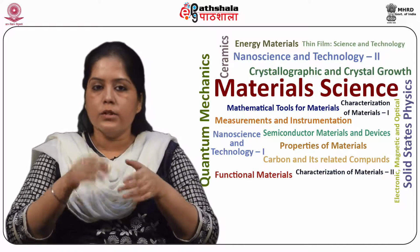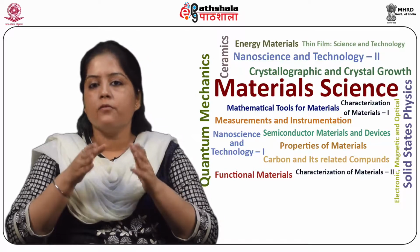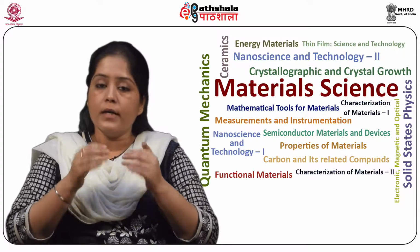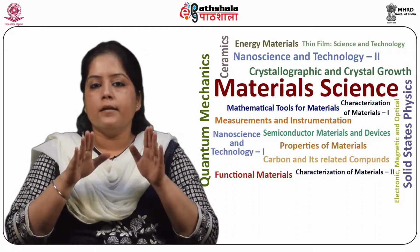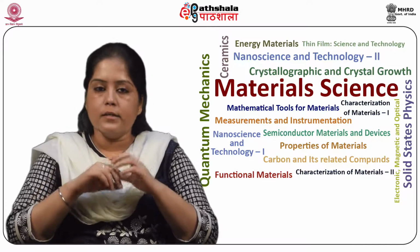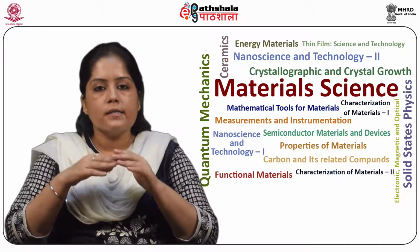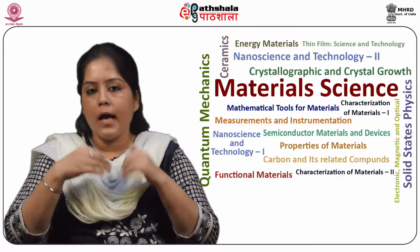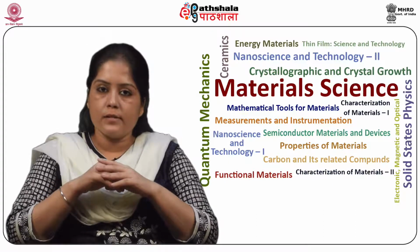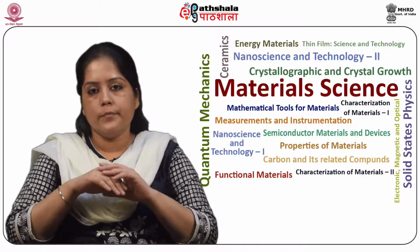These include: first, hysteresis in strain field dependence is minimal or negligible in a selected temperature range. Second, deformation in materials is more stable and comparable to piezoelectric ceramics. Third, no poling is required.